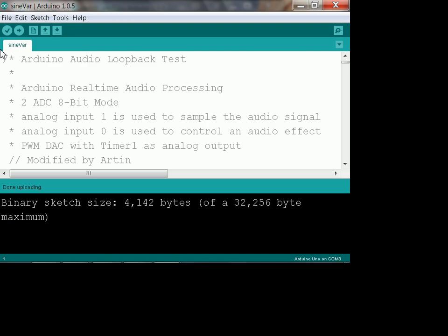Now another way you can do it is you could fabricate the R-2R ladder in silicon. That's a lot of times what people do when they build DACs. Sometimes they even trim the resistors with lasers, and these are called laser trim DACs, and they can give you very good accuracy. Analog Devices, a company based in Massachusetts, used to make laser trim DACs that we used. There's another way to do this, very fast. DAC is called an op-amp based DAC, right? And that'll give you some reasonably good results.